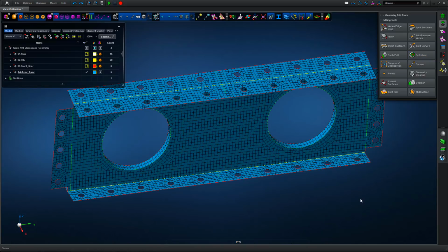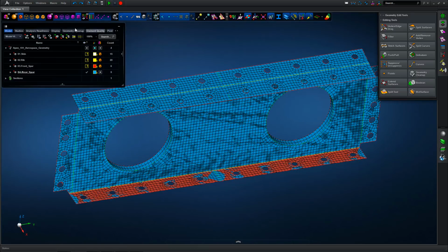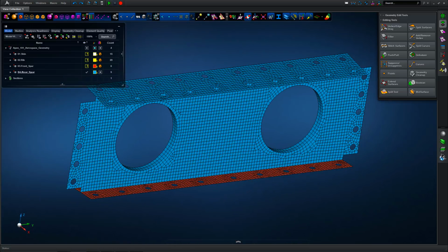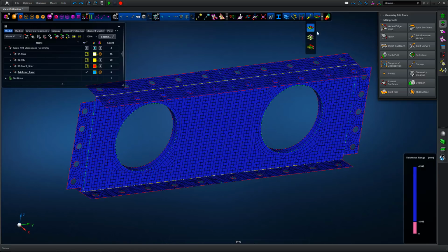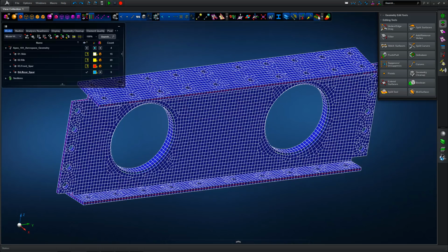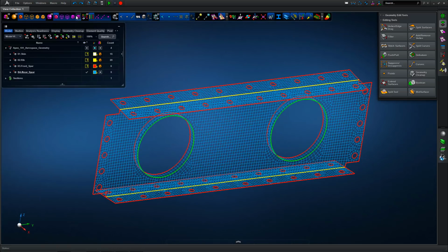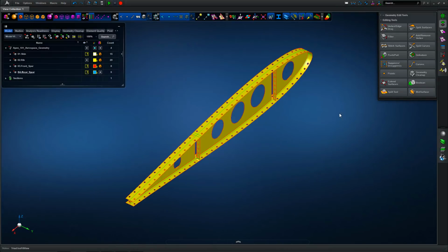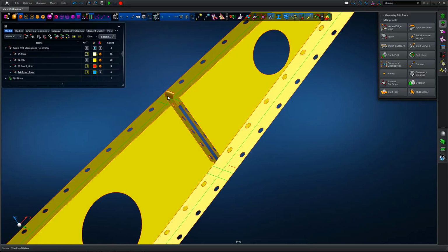In this case, we're going to use what's called a hole-to-hole fastener definition. Thereby we want the fasteners modeled explicitly within the meshed entities. So checking surface normals first of all. Happy with the surface normals, we can flip things around or check consistency if required. Looking at the element properties, similar to previous, however the properties have been maintained with all the surface edits and geometry manipulations that we've looked at. We can check model topology in terms of free, shared and manifold edges based on the mesh rather than the geometry. So that completes the rear subspar.